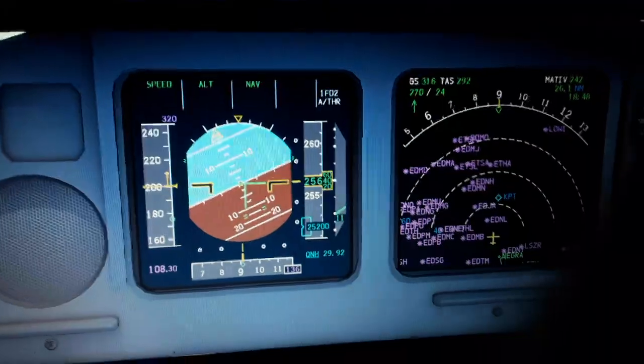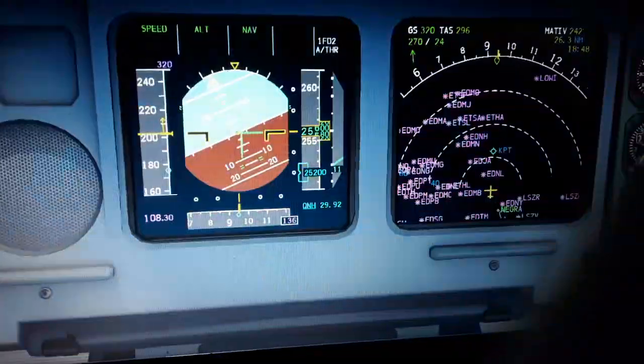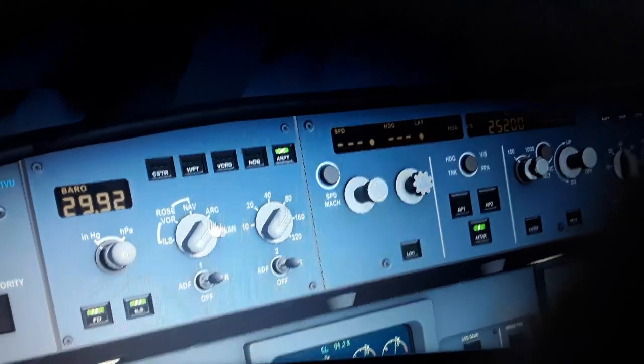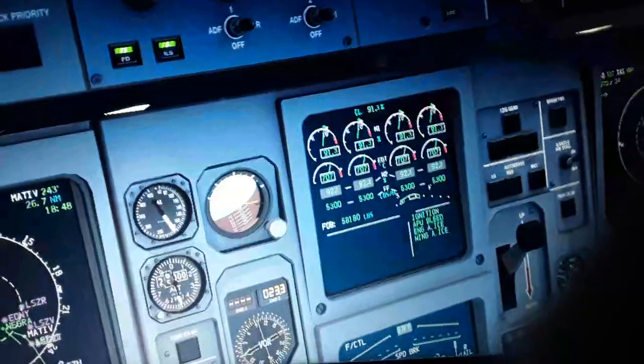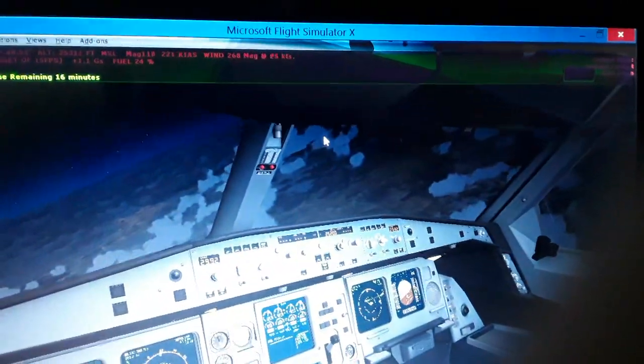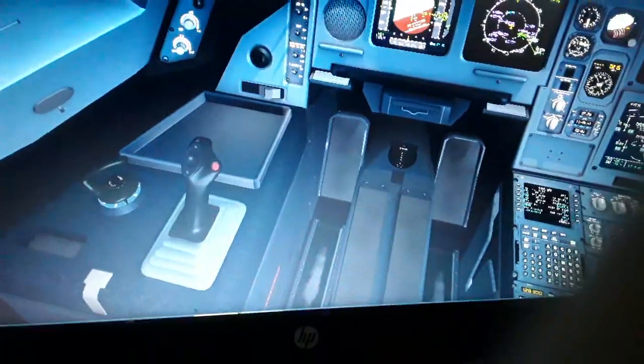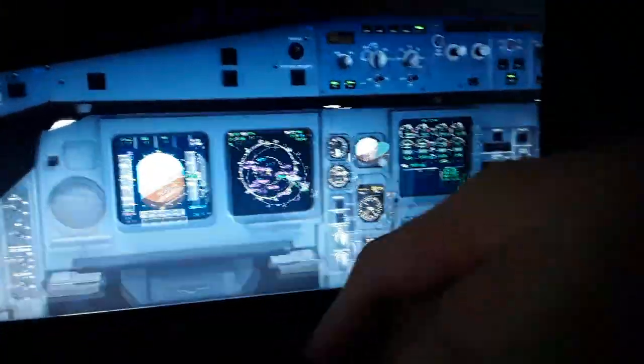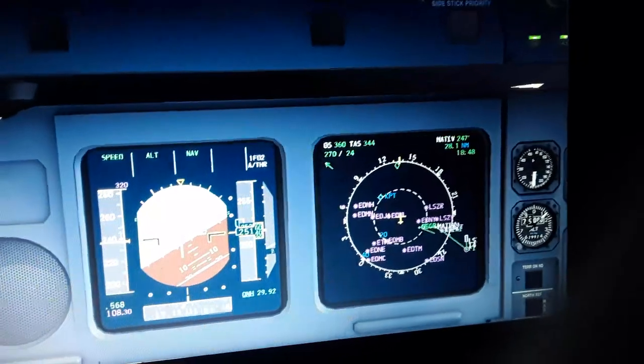Maybe track the flaps now, because it makes it harder to hold a position here. Let's see how far away we can see here as we turn. And this is how we maintain a bank roll at this altitude with this airspeed, using the fly-by-wire system manually, like that. We request a zero acceleration for this airspeed and altitude.